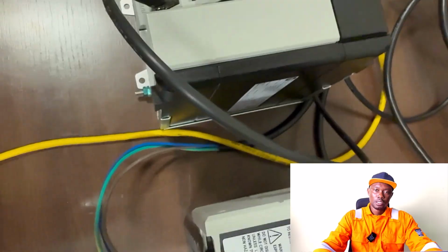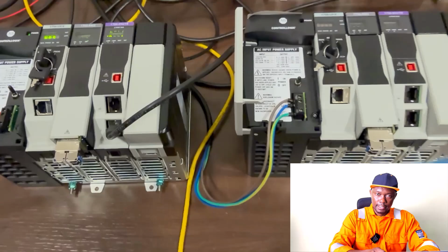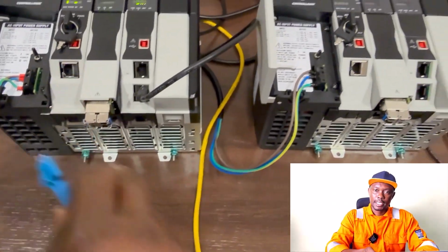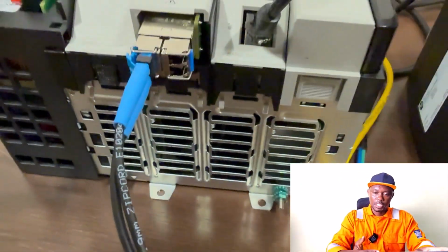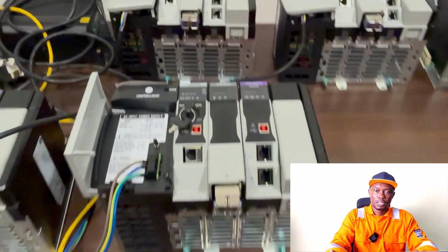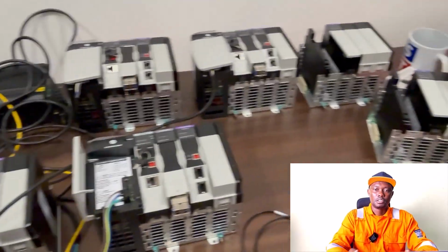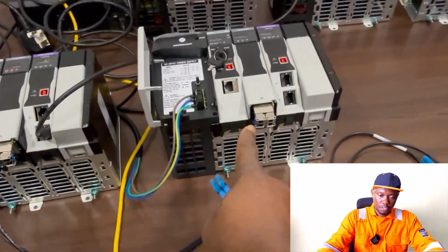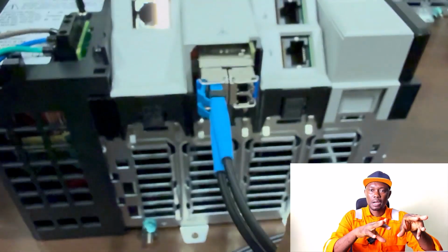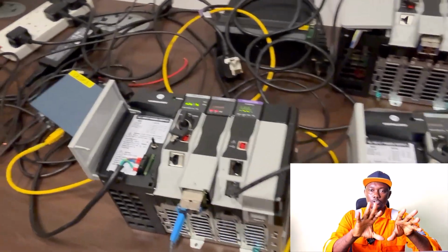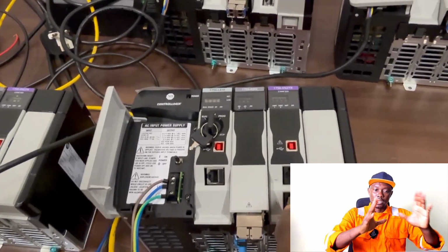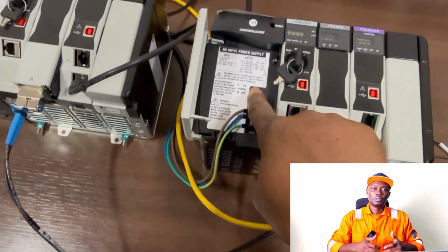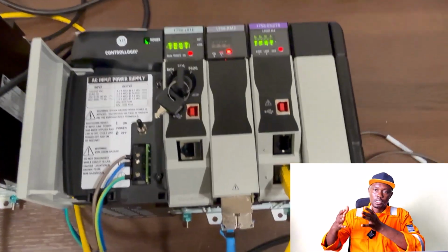Okay. So after the download, you connect the redundancy cable, the fiber optic cable. Rockwell provides two of these cables for high availability and reliability of the system, making it more robust. Also, when you are downloading on the primary at that initial time, you do not connect or turn on the partner. So after the download, you connect the cable, then you power up the partner.